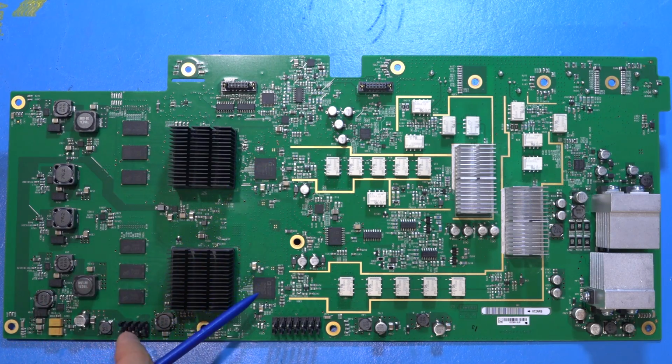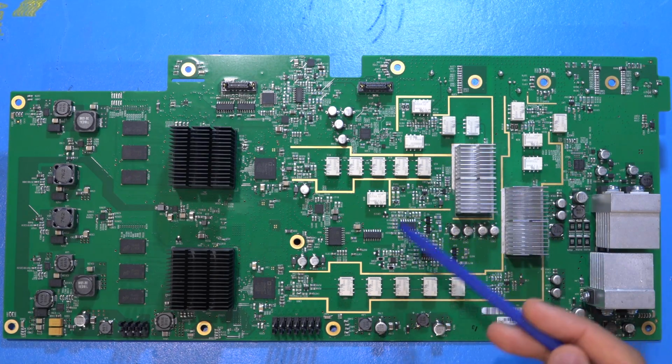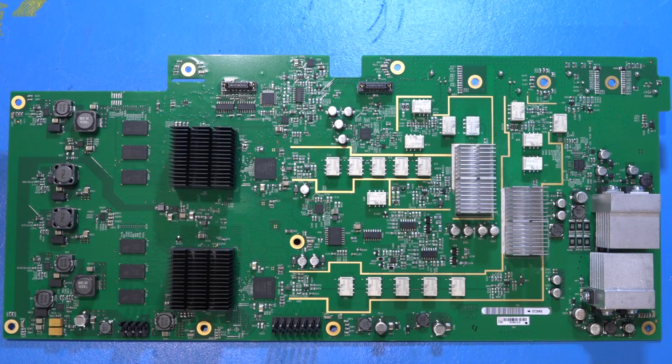As you can see, we have two completely independent channels, and the output of these DACs are then taken into a series of mechanical relays and switches and attenuators in order to meet the different output amplitudes and working operation of the circuit. This is very common. You've seen me discuss this when I've taken apart different kinds of arbitrary function generators. This is a good way to achieve very high linearity and dynamic range by using these mechanical relays.